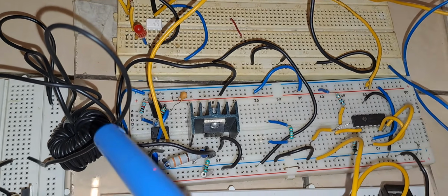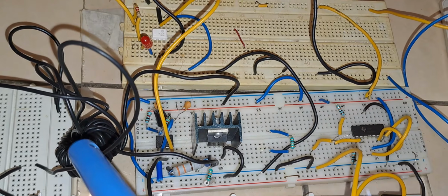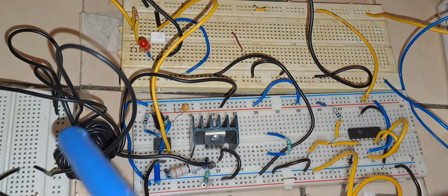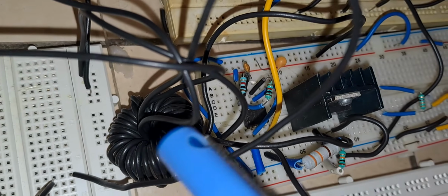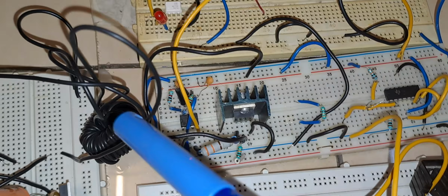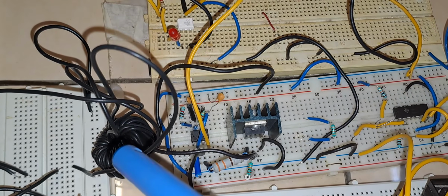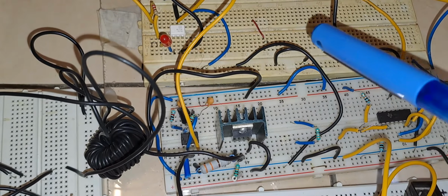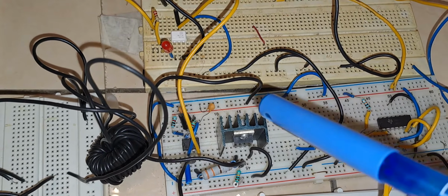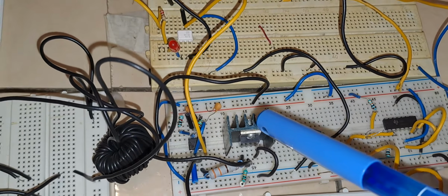The transmitter transformer. This transformer is in the transmitter end. So this is the transmitter transformer. This is a high frequency transformer wound on a ferrite core. As you can see, it has 10 turns in the primary winding and 10 turns in the secondary winding. So one end of the transformer is tapped with the 12 volt DC bus and the other end is connected to the drain of this MOSFET.